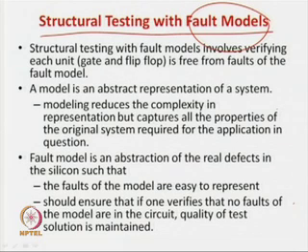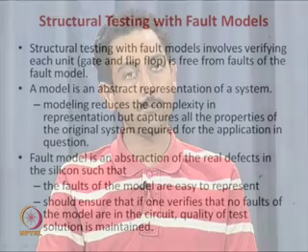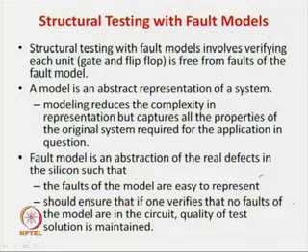So, what we will verify is, given an AND gate, we will assume that it does not have any fault from the fault model. We will elaborate on this, but the philosophy in structural testing with a fault model is that we will not even think that an AND gate is an AND gate or a full adder is a full adder. We will completely forget about the functionality of the units. So, what is a model basically?